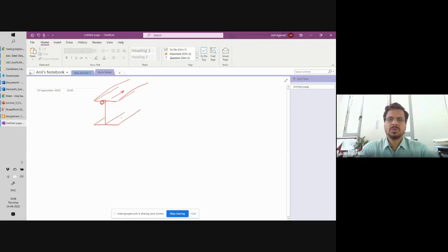So this is one type of global imperfection. You may have global imperfection in the minor axis, like it is shown here. You may also have global imperfections in the major axis. That is, your web is bent in its plane. So these are both global imperfections. Also, you may have something like a local imperfection.